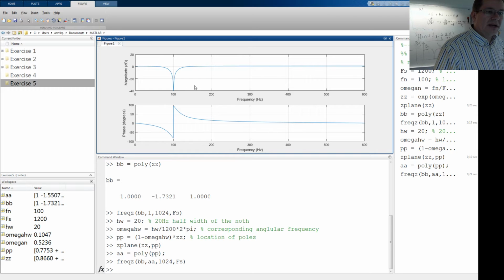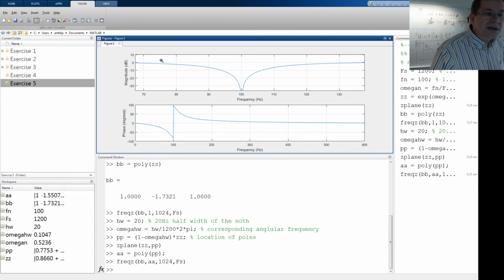And there, basically, let's take a quick look. I would say it's about 20 dB. I should take this one out somehow. Figure. Oh, there are the tools. There we have. Seeing is believing, so 20 dB, minus 20 dB and plus 20 dB, so it's about the minus 3 dB point here and here.